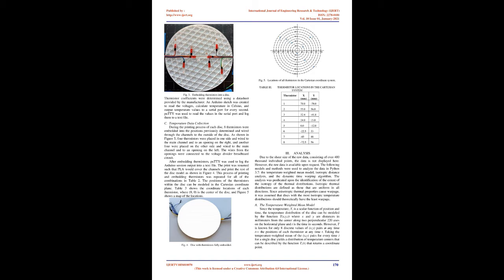Lines and trihexagonal patterns as well as 10%, 20%, and 30% densities were chosen because of their common prevalence in commercial 3D printing. B. Temperature measurement system. 8 voltage divider circuits were designed and built on a breadboard using an Arduino Mega, 10 kOhm resistors, wiring, and 20 kOhm NTC thermistors from Vishay/BC Components, model number NTCLG100E2203JB. Figure 2 shows the basic wiring for the voltage divider circuit used.